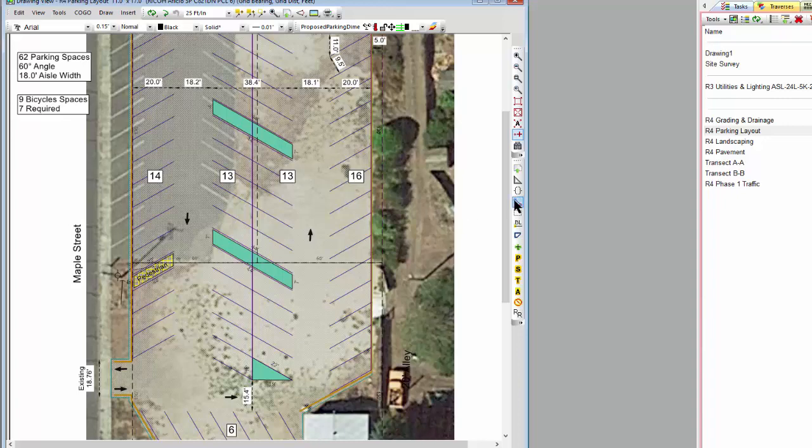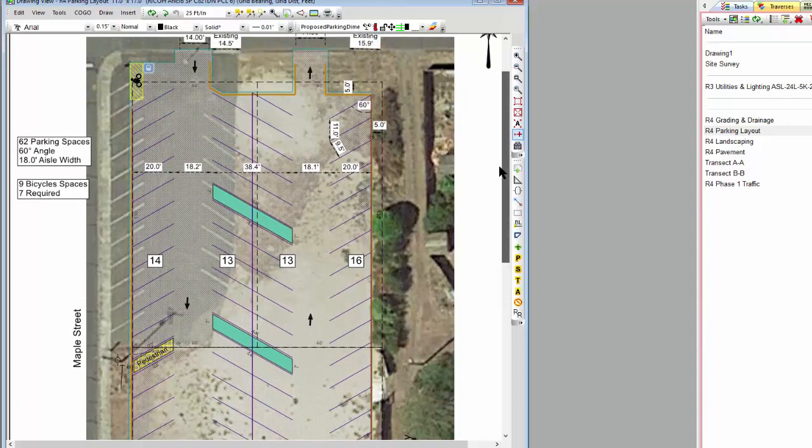Paving and curbing, okay? You can see I've got this brown line for all the curbing here. Everything that's uphill is solid curbing. Everything that's downhill on the flow has to be segmented curbing so the water can run through it into the bioswale. So we've computed our lengths for all that for the bid item on that.